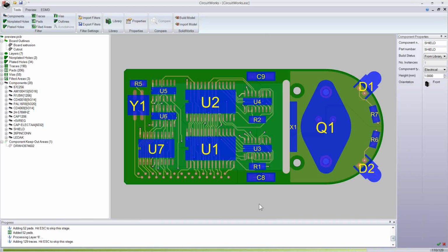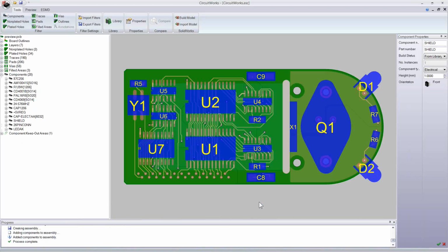While this is happening, I want to talk a little bit about one of the other capabilities in 2013. If you've upgraded to SolidWorks 2013, you can actually save SolidWorks 2013 files and open them in SolidWorks 2012 Service Pack 5. So we give you the capability in SolidWorks 2012 Service Pack 5 to open a SolidWorks 2013 file, but it opens it as though it was an imported file, so there's no ability to modify any of the features or actually even see any of the features on the component. But it does give you the ability to put it in assembly and do other in-context